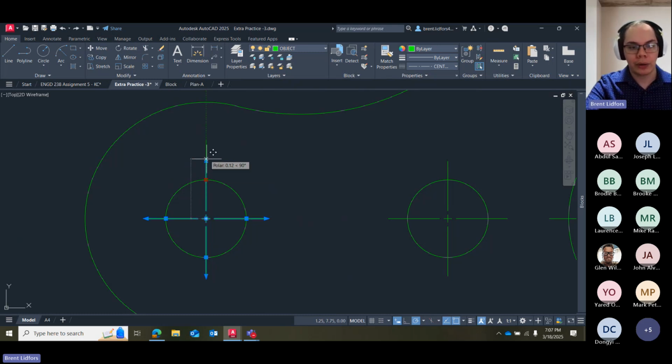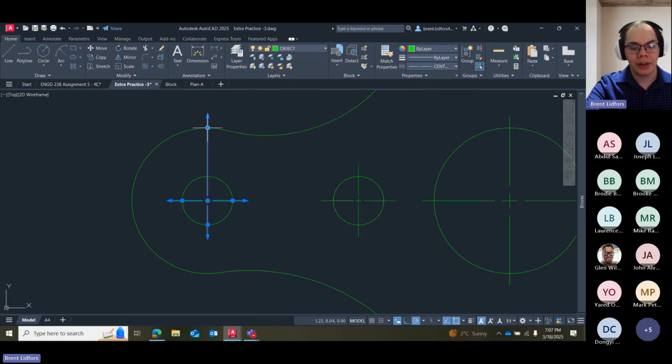So I can grab the square grip, move it up to the top here, where it intersects with the other quadrant of the larger arc. Moving these grips around here and just extending them. And then that arrow portion is just the extension that sticks out the end to show that it's still a center line. If this meets with the end, I kind of bring it back.